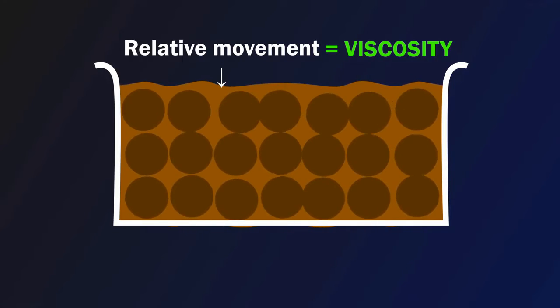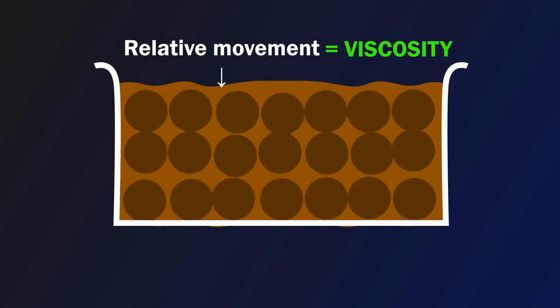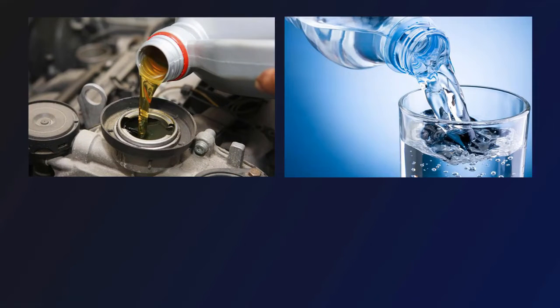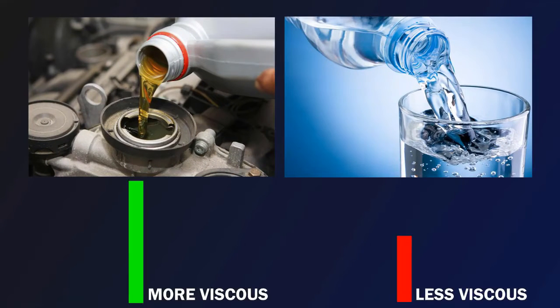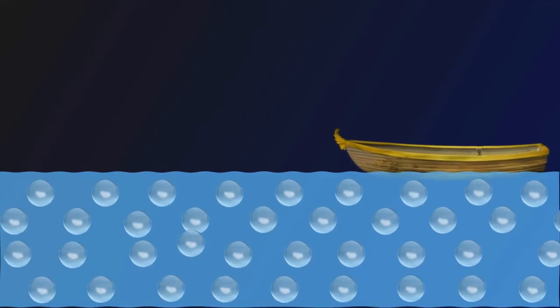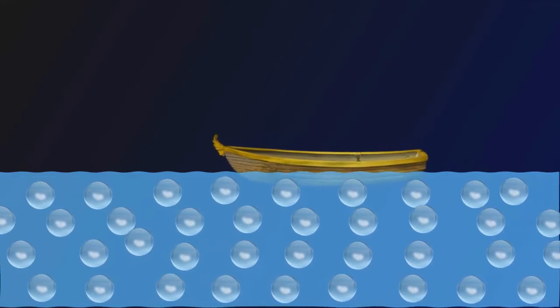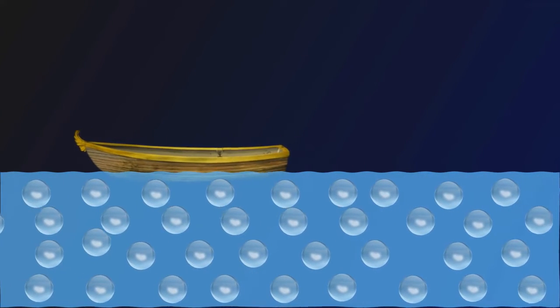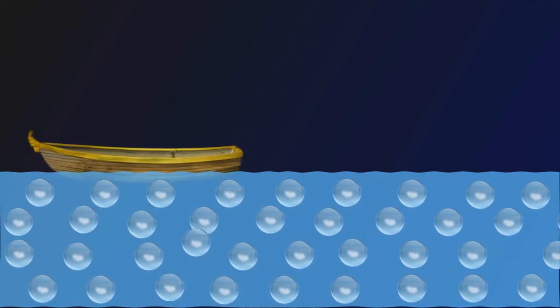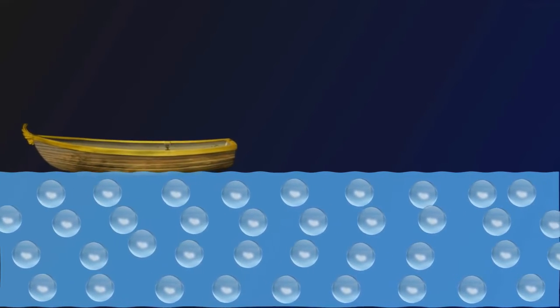The first class is viscous versus inviscid regions of flow. When two fluid layers move relative to each other, a friction force develops between them, and the slower layer tries to slow down the faster layer. This internal resistance to flow is quantified by the fluid property viscosity, which is a measure of internal stickiness of the fluid. Viscosity is caused by cohesive forces between the molecules in liquids and by molecular collisions in gases. There is no fluid with zero viscosity, and thus all fluid flows involve viscous effects to some degree.